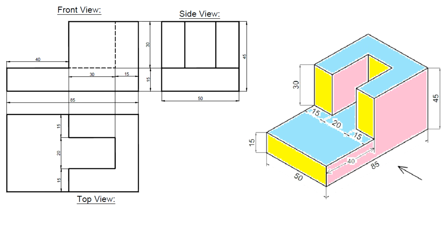This is 85 by 45, so draw 85 by 45 on the drawing, one view, and then we need to draw another principal surface which is behind this, but this principal surface will not be visible in this direction, because when you try to see that, this surface is hiding this surface, so this becomes the hidden surface.